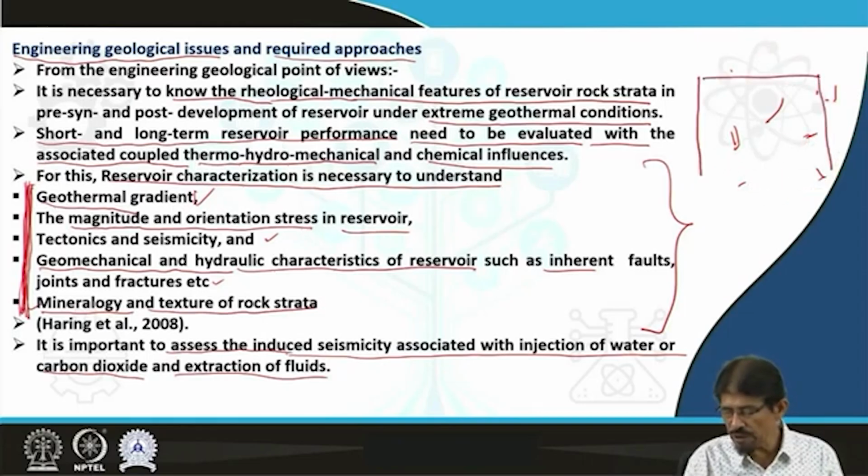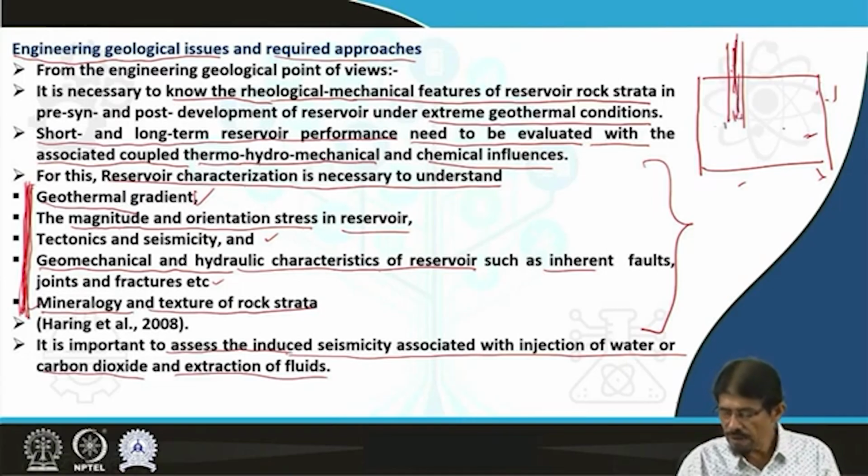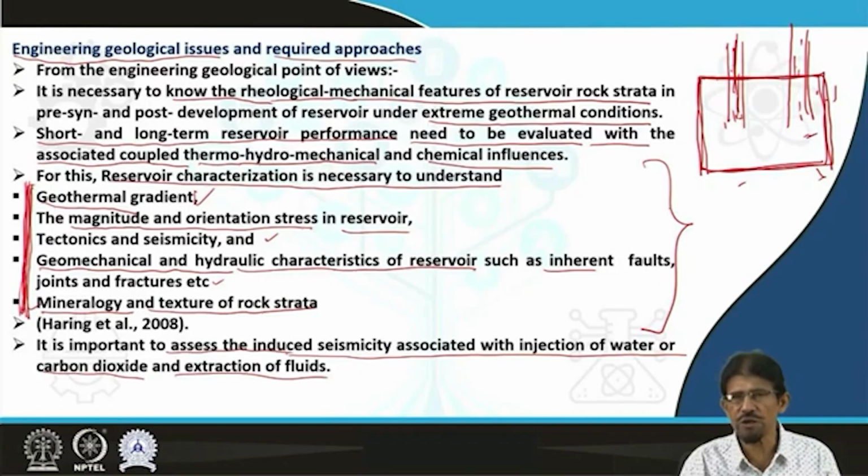In such a situation, this strata is subjected to an increment in pressure due to injection of water and a decrement in pressure due to extraction of hot water. So this system experiences a cyclic type of stressing. And friends, under cyclic loading, any rock strata or even any rock is going to show reduced strength.